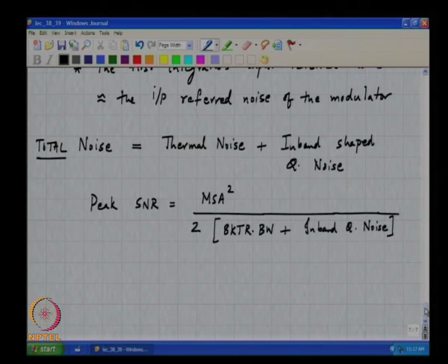All right. Please note that everything here is under our control, right. This can be reduced. One can keep this the same and reduce the thermal noise by impedance scaling the first integrator. One must bear in mind that reduction of the impedance level means increase in the power dissipation by the same factor, all right.